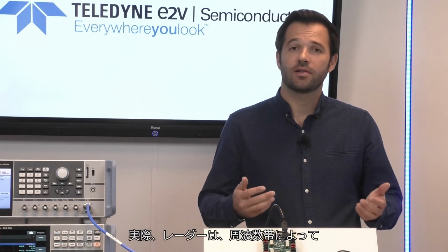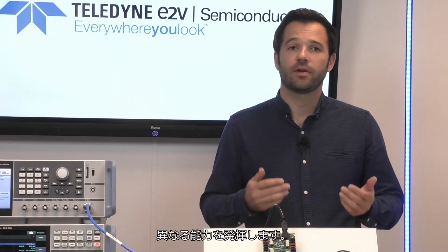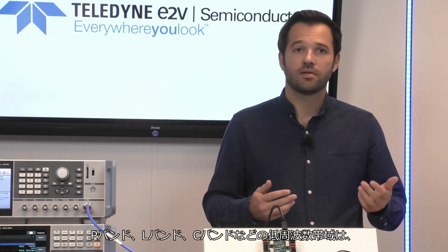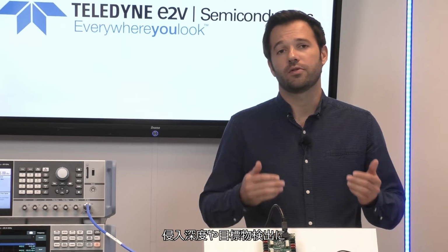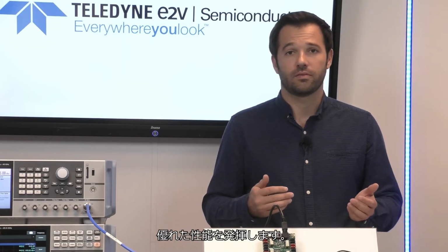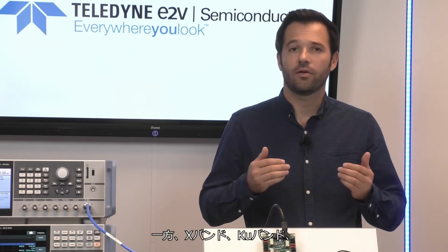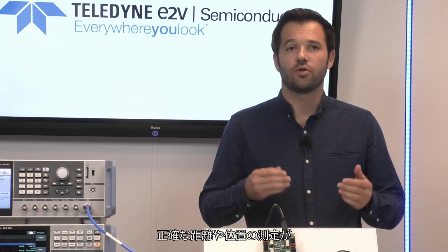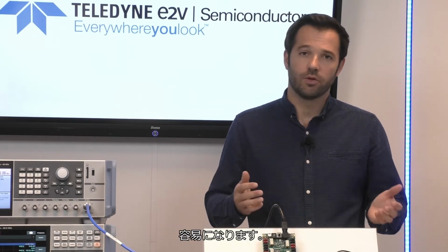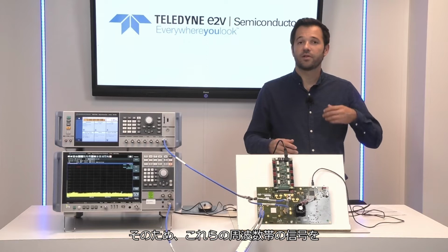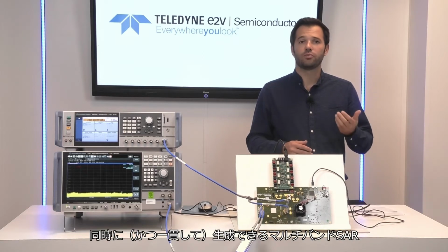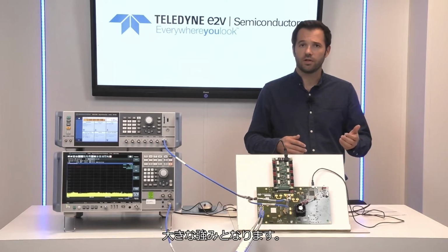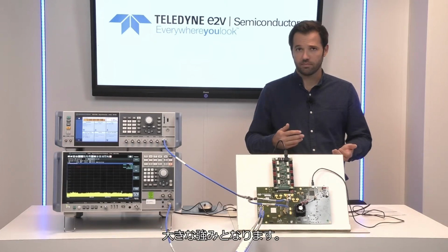Indeed, radars have different capabilities at different frequency bands. Lower frequency bands like P, L, and C bands offer better performances on penetration depth and on targets detection. While with higher frequency bands like X, Ku, and Ka bands, it is easier to obtain accurate range and position measurements. So, there is a definite advantage in being able to develop a unique multiband SAR imaging system capable of generating signals in all these bands simultaneously.